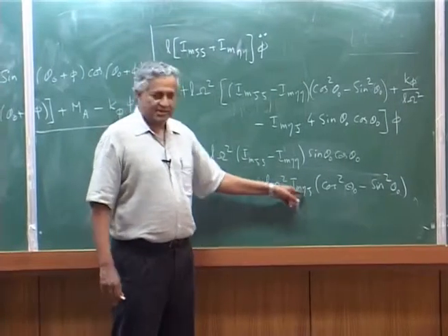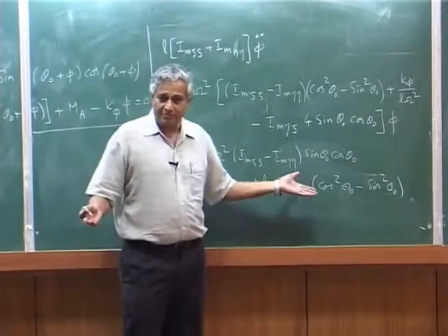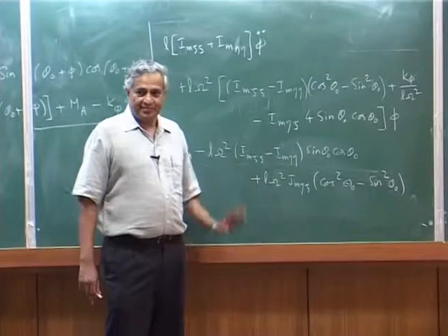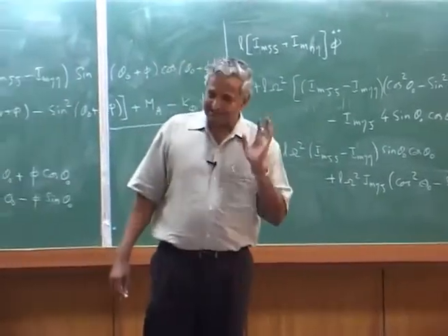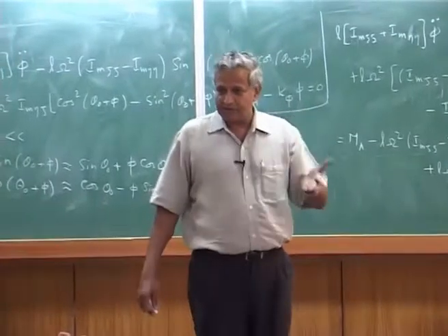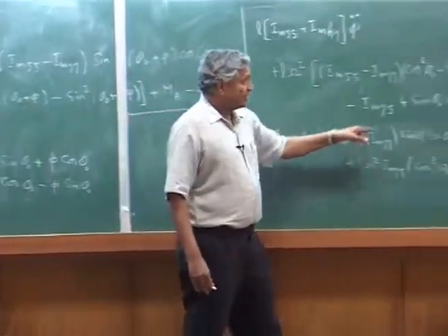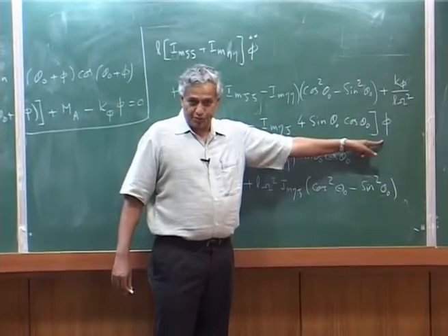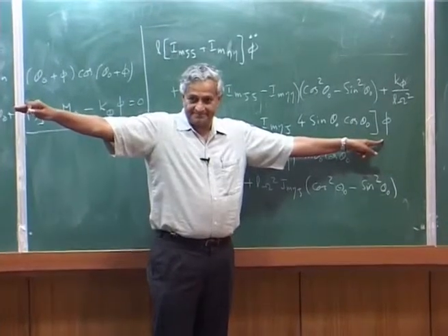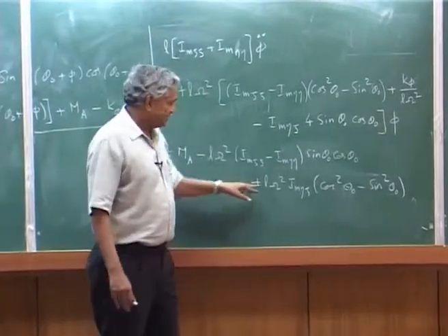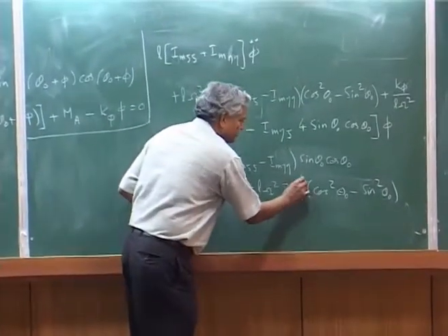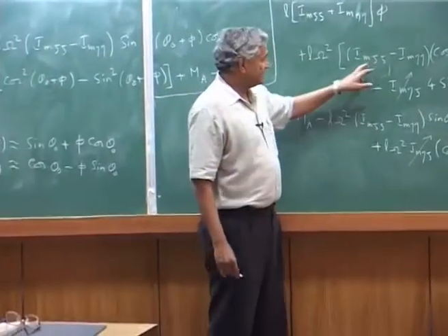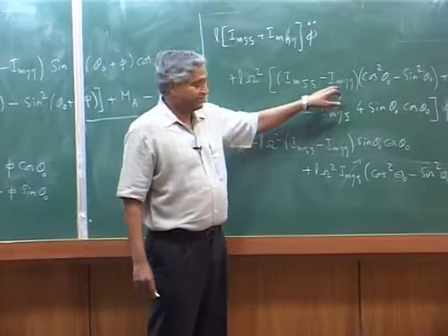Okay. This is a cross product. If it is a symmetric cross section, then that will also go off. But if it is a non-symmetric cross section, you will have some term. Okay. But usually you take a symmetric cross section of the aerofoil. Then you can always find what is the elastic twist phi due to a pitch angle. And because this is usually a small number, you can neglect it. Okay. And even this quantity is larger than this quantity.